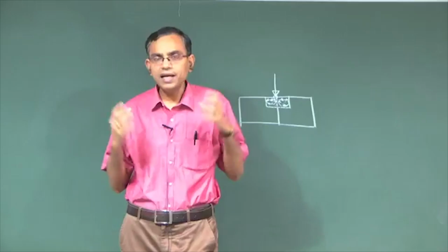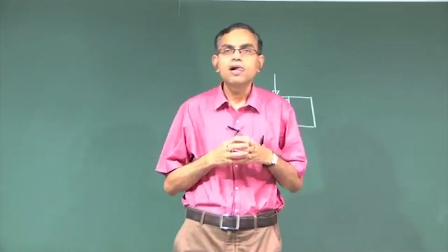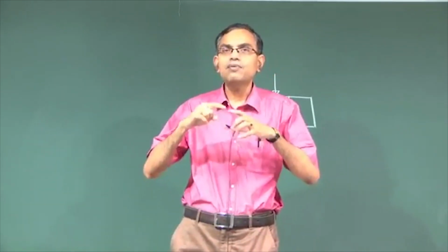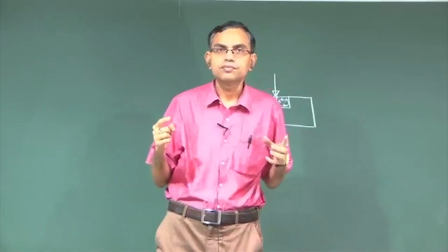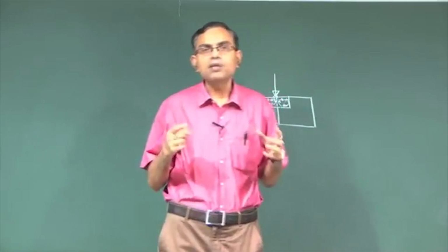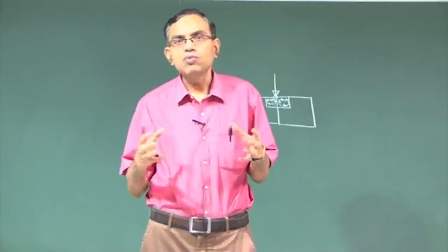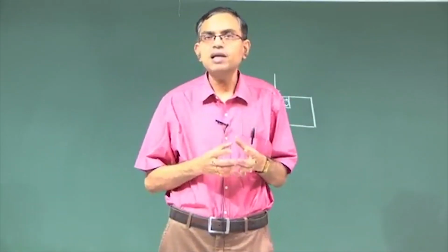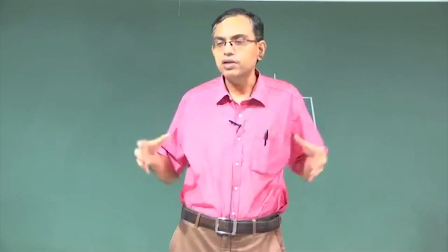The whole idea of having a hydrophobic coating is that on the top you have a nice droplet which is formed. If you have a droplet which is formed, the contact angle will be high, and then we will see how by applying an electric field we can lower the contact angle.